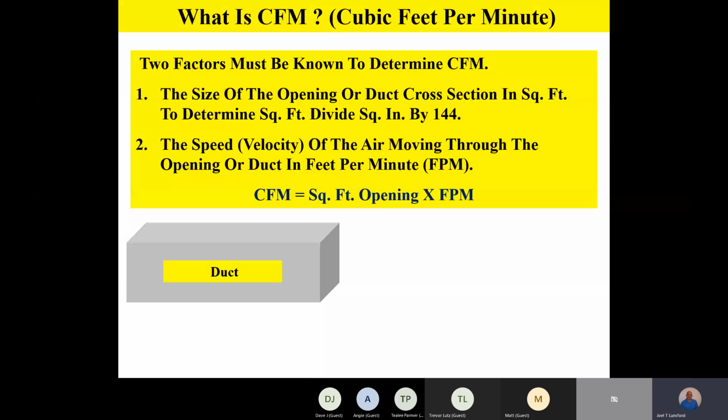All right, so as we take a look at the air duct calculator team, one of the first areas we're going to look at is you're going to find on your air duct calculator, there's going to be a window, and as you turn this air duct calculator, or if you have one that slides in and out, you're going to be able to find velocity in feet per minute at any given CFM. So on that air duct calculator, you're going to be able to line up velocity and required airflow